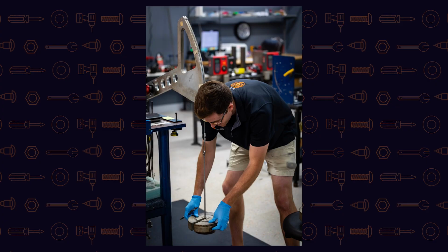In this example, it looks like a 2-foot wheel or 2-foot segment arm, and we're hanging weights. So whatever the amount of weight is, multiplied by 2, that would give us our foot-pounds. We do this at different points throughout the range of the sensor, and that is all calculated through the processor, giving us our torque output for the actual reading on the torque analyzer.